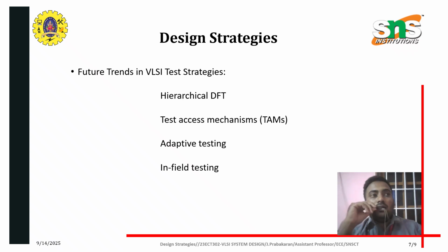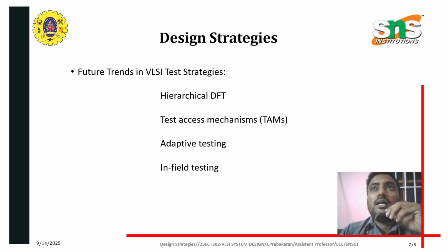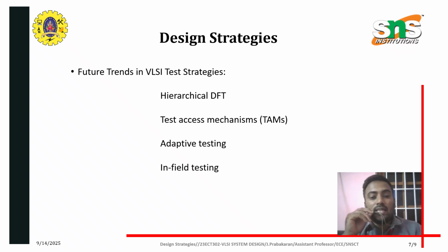Generally, design strategy in VLSI testing revolves around increasing controllability, observability, and automation of test using scan-based testing, built-in self-test, and boundary scan test. Also test compression and low power techniques, all while balancing cost, area, and performance.